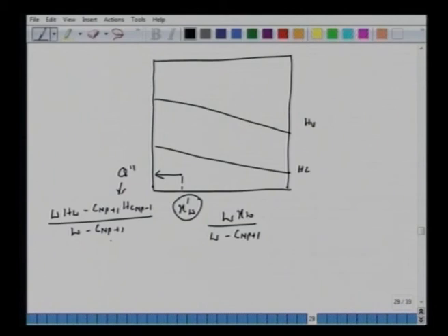So with this, now we can connect. This is your y(np+1) equal to 0. So we have G(np+1) on this axis. We connect with this new del point. Once we have this, then we can construct our new tie line, which will correspond to G(np). Again, we connect here with this, which is L(np-1), and so forth. We can construct. All right. So this is the discussion we had for this open system.